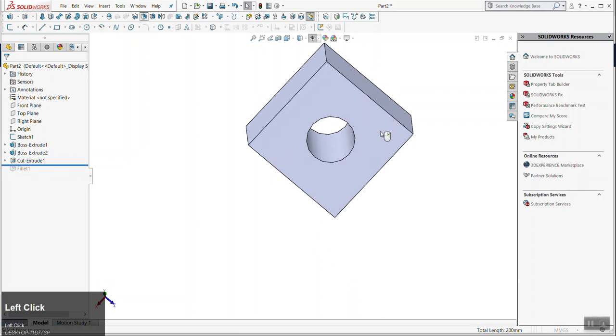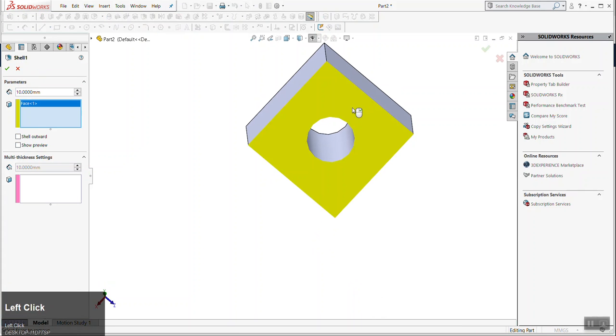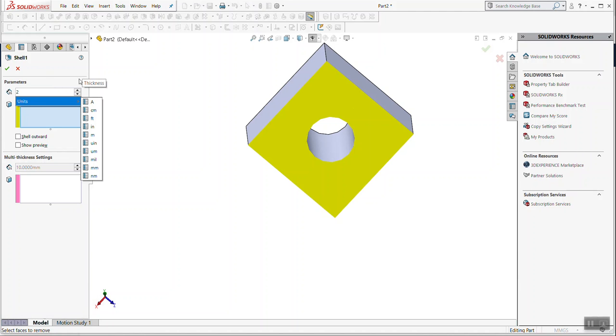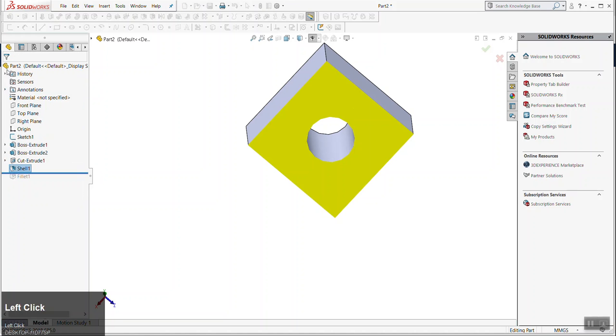can just look at this. Again, I'll look at my drawing. I think it's a 2 millimeter wall thickness. So again, you hollow it out to an even thickness, as Tom said. The thickness is referred to as a wall thickness. So this olive oil bottle has a wall thickness. I'm going to guess it's something around 1 millimeter. That might be too thick. Cut it in half and measure it. Anyway, this drawing is telling me to make this 2 millimeters thick.